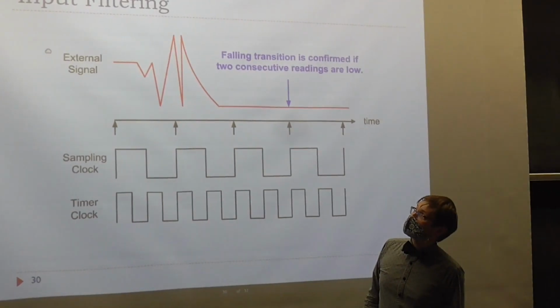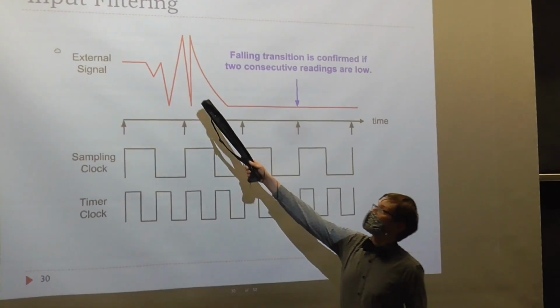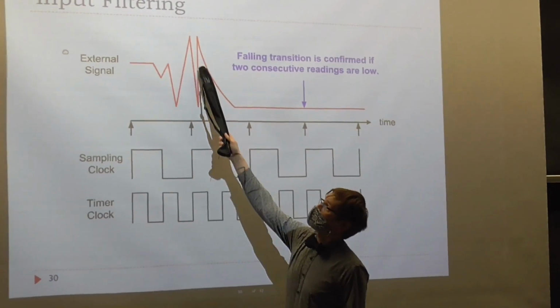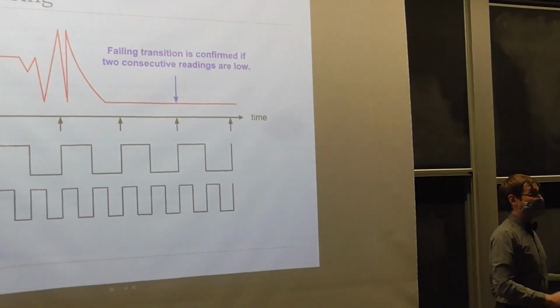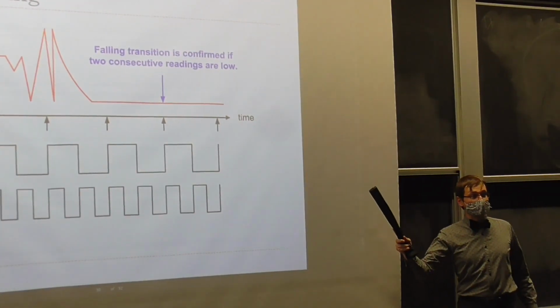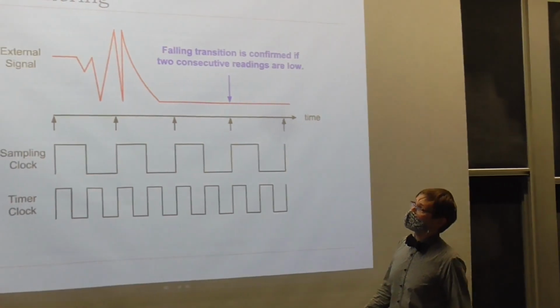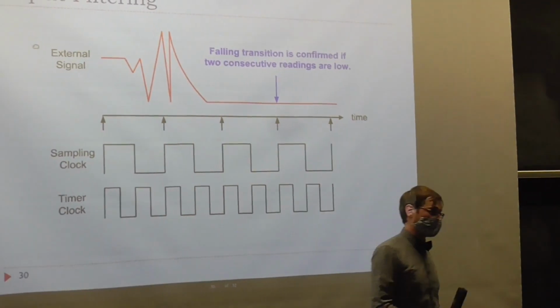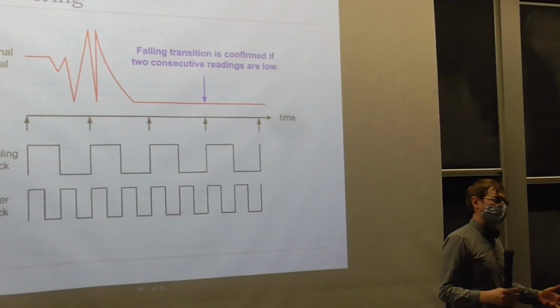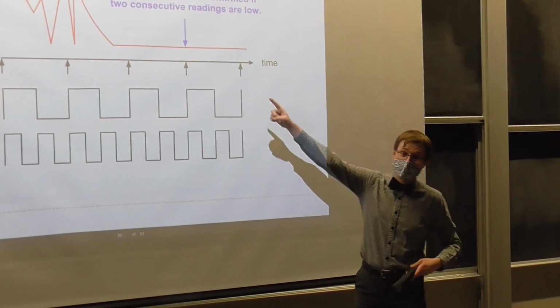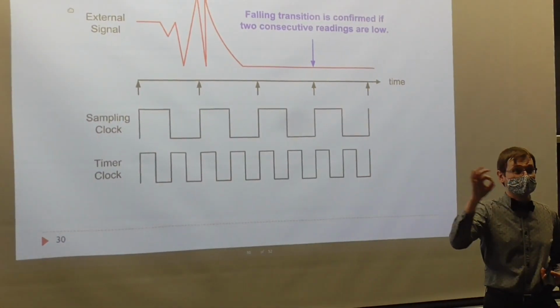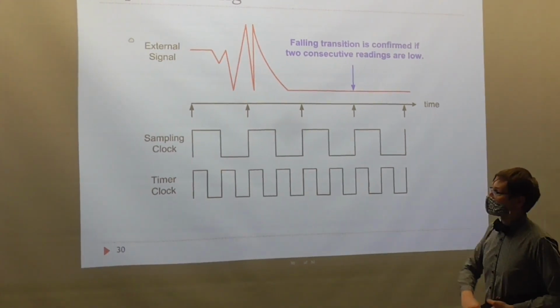And if you're thinking it's a little bit weird that the voltage level actually jumps up above 5, or whatever the baseline high voltage is, that's actually not as unusual as you might think. These types of things can sometimes be caused by mutual inductance and electromagnetic interference. So sometimes you can actually see voltages that pop up a little bit over the baseline signal.